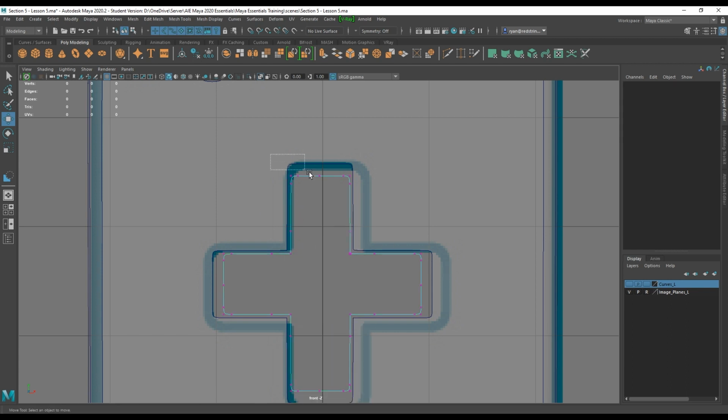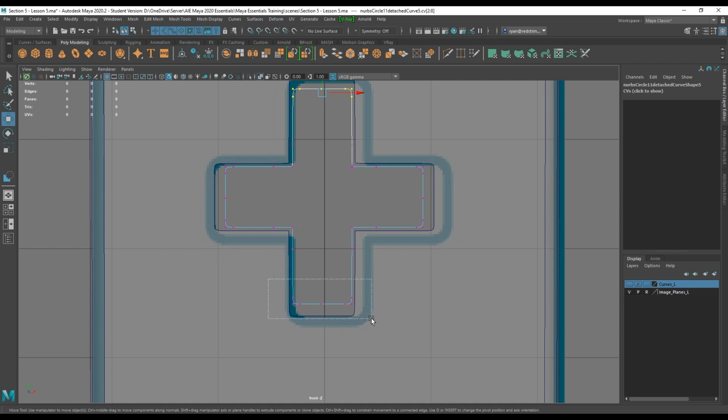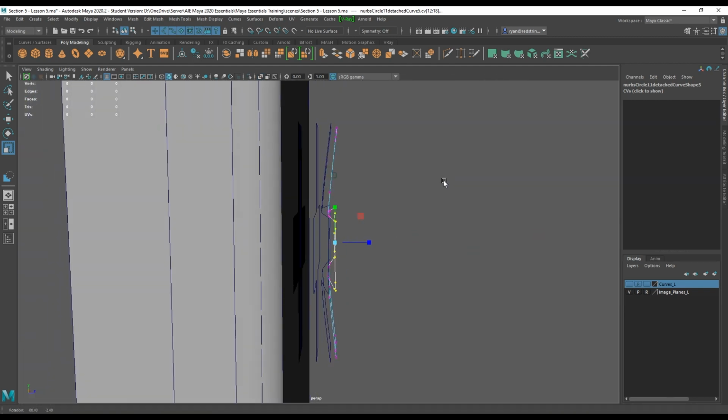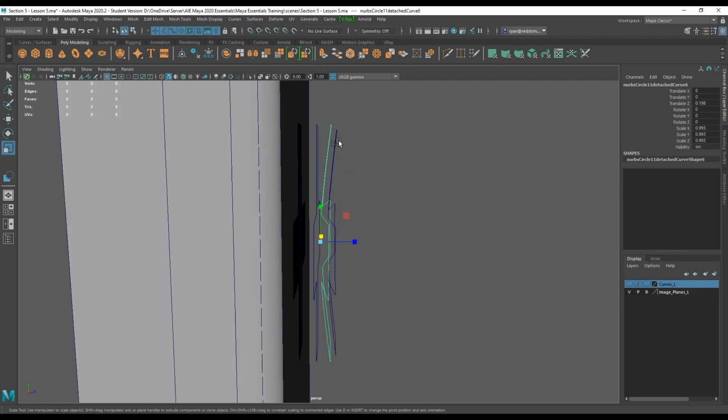I'm going to right click, control vertex, grab that bunch, and scale them out so it's uniform, because that's going to create a problem, and scale them out a bit. Oh, not that far. Try and get them as far as the top ones here. Now if I look here, you see we have less of an issue. So let's try our loft, shall we?